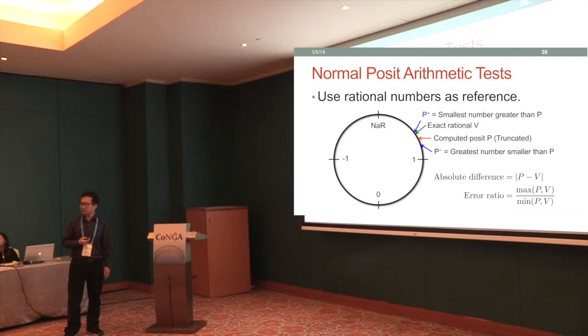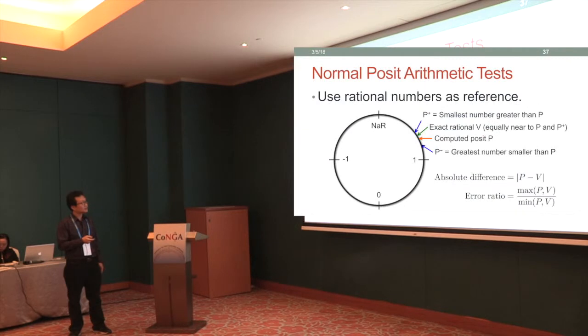If you are rounding the fraction bits, we use the metric absolute difference. The correct answer should have the corresponding minimum error. In this case, the exact value is exactly at the midpoint of the two consecutive posit numbers. So we can check the least significant bit of posit P for 0, because in this case, we should round to even.